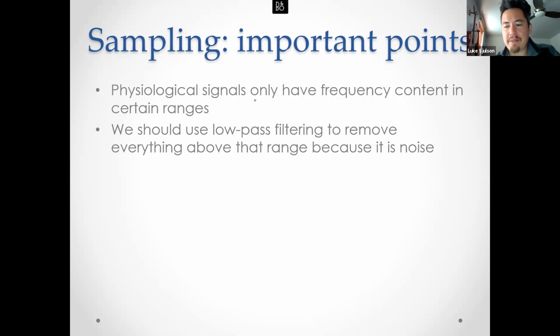So if you have an amplifier that only goes up to, say for example, I have these fiber photometry photodiode things that have really slow amplifiers, and the bandwidth of the amplifier only goes up to 70 hertz, which is infuriating. So I don't need to low pass filter that, because the amplifier is basically a low pass filter, and I would have to sample that at more than 140 hertz. I'm sampling at 20 kilohertz because it's just more convenient to do it that way.